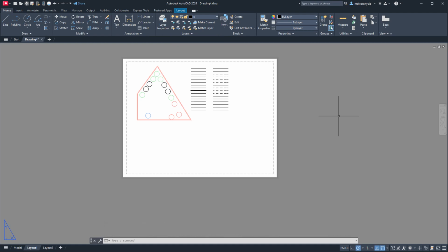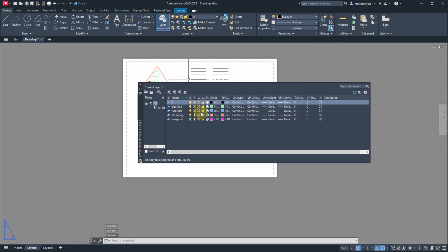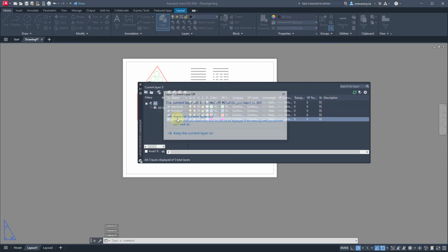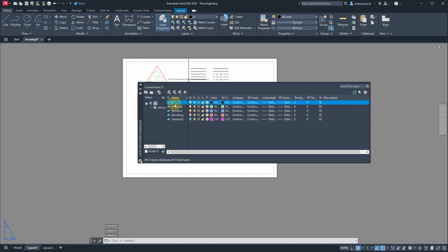And so it's usually a layer that I will have as a fuchsia. Something that helps with sorting is, nope, stay on 0. If you put the little squigglies at the front and then sort, you usually get them above the 0 layer right here. So if there's something that I really want to keep an eye on, I'll add squigglies to it. So if I'm doing this with electrical and then resort, I've got my squigglies at the top here.